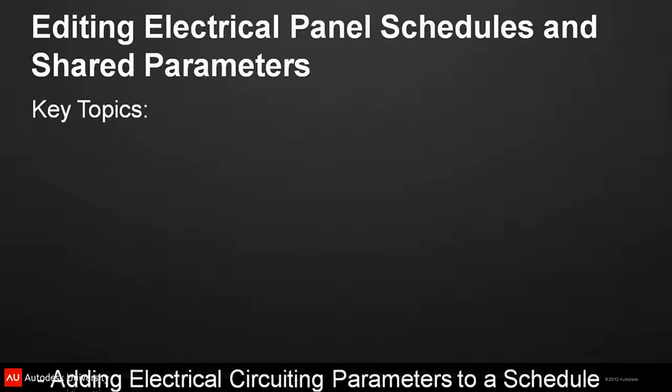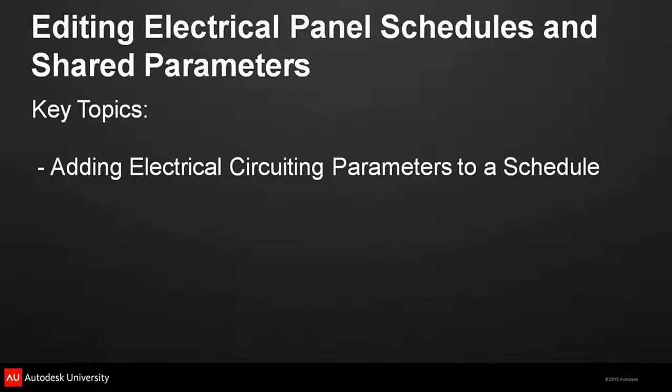Let's talk about panel schedules real quick. How many of you guys are actually doing panel schedules and customizing them? How many of you guys like to use wire sizes in your panel schedules? How many people don't like to use the wire sizing tools in your panel schedules? Okay, you got to know how to set up all the electrical settings to make this work correctly.